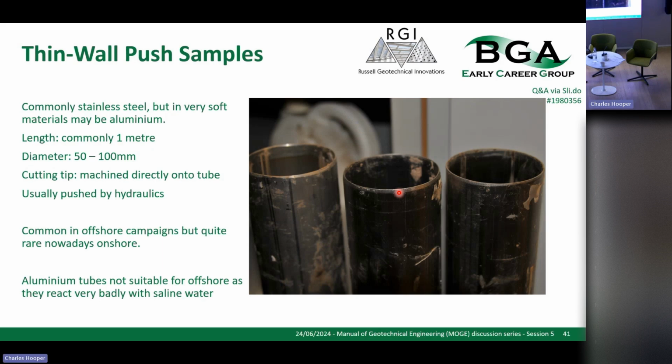Okay, a different type of sample is the thin-walled push sample. Offshore, they're very, very commonly around 70 millimeters, but they can be used onshore at 70 millimeters to 100 millimeters diameter.